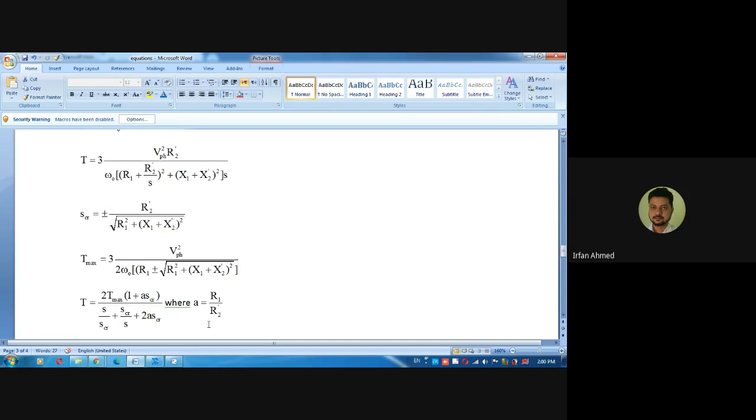Basically, the rotor current will become greater than the rated value beyond this point. If you increase torque beyond this point, the rotor current will increase beyond its permissible value. I think that is the breakdown. That will cause the breakdown. What type of damage will be there, sir? Will any winding burn or anything else? If the current increases above the rated value, your insulation will get damaged. Heating. The motor will get overheated.